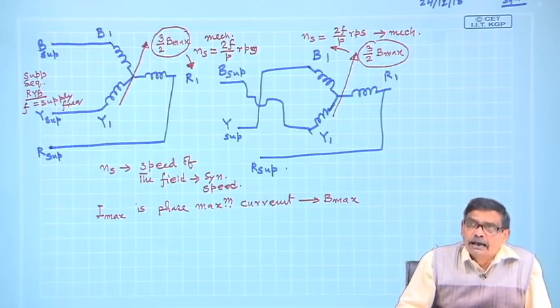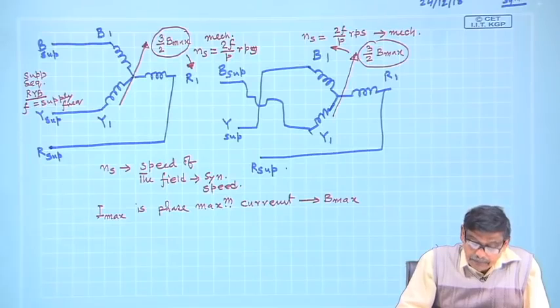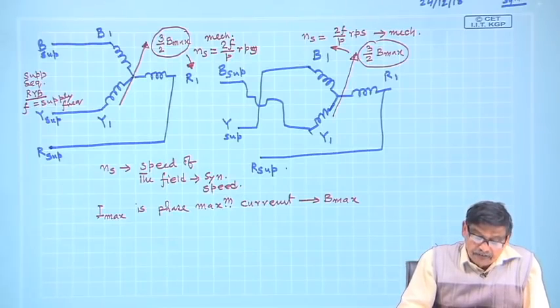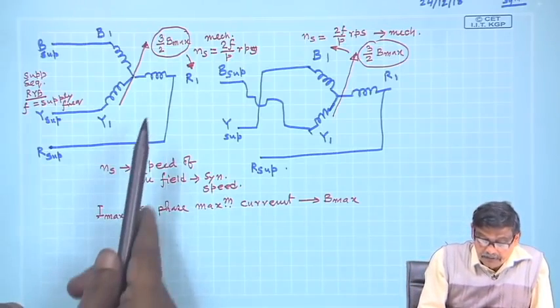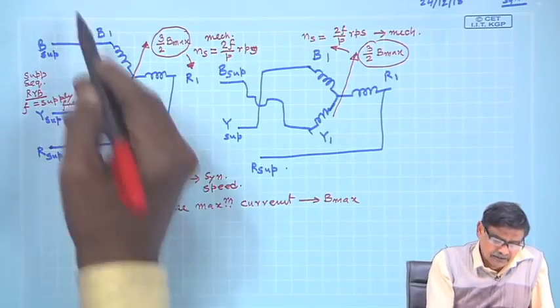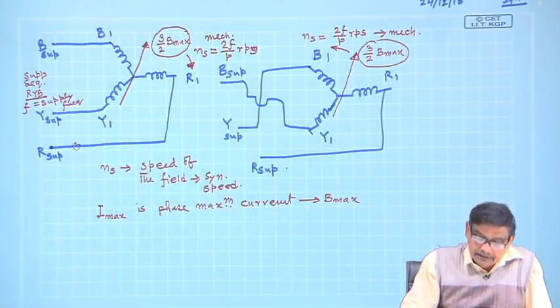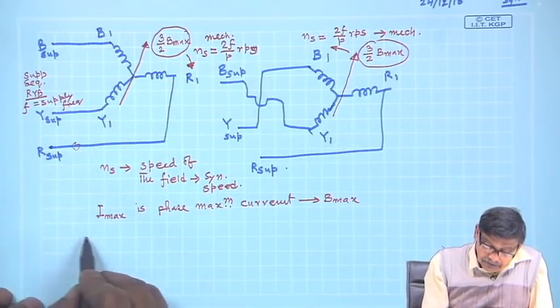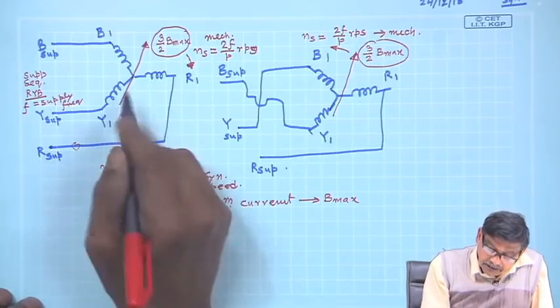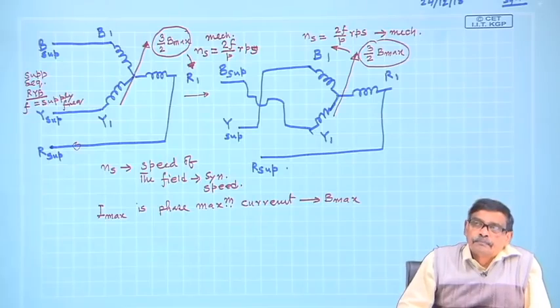But about one thing I am pretty sure, that is what I am trying to tell. If right at this point of time, these currents I can see in the oscilloscope, if the R phase current is maximum value I max, then I am sure the resultant field will be along the x axis.